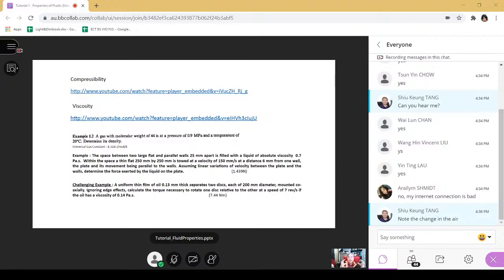So remember, when we compress the bottle, and the bottle contains air and liquid, the liquid is being compressed at the same time. There could be a very small change in the volume of liquid, but the pressure inside the liquid is the same as the pressure inside the air, because they are packed together. So there is an increase in pressure in both air and liquid. So far that is about compressibility, and the first example we dealt with is the equation of state. I will go back to this later on after we finish the second video.